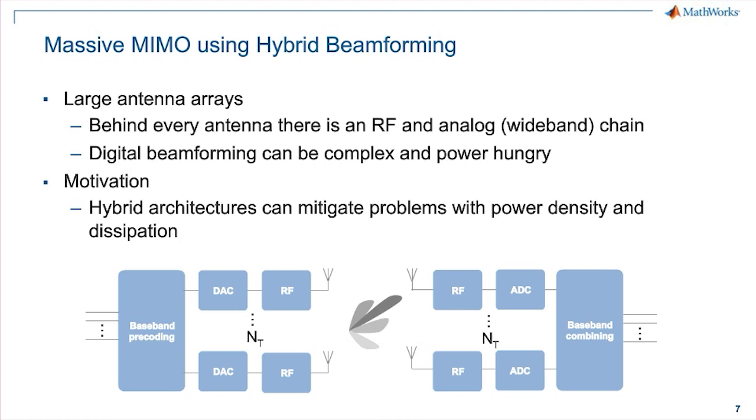In spatial multiplexing, we are using multiple streams or, in the nomenclature of 5G, multiple layers. But what they have in common is that you can implement beamforming in a way that each of those baseband IQ samples that arrive at each antenna port can have underneath it an RF chain, where each of them has its own RF amplifiers and so on. That becomes complex and power hungry.